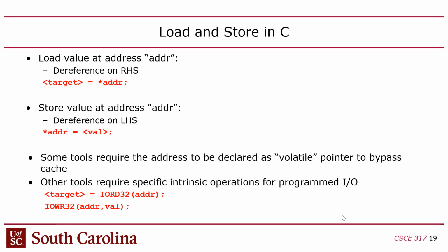If the address is an I/O address and you do this, it may get caught up in the cache. And you don't want to go in the cache. I/O load and store instructions are supposed to bypass the cache because the cache is only for memory. These aren't memory. This is a control status register. This is a transaction I'm doing directly with hardware. It shouldn't be caught up in the cache. The cache shouldn't be a factor here.